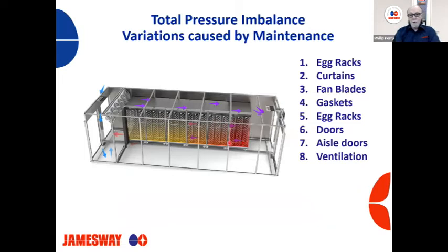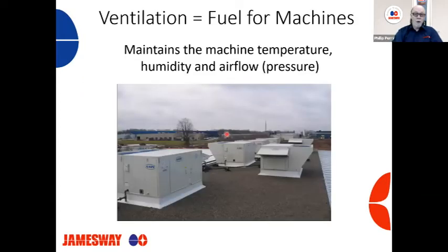Ventilation. I want to take a little bit and talk about the ventilation aspects of the machine, our intake and exhaust. It's very important to the operation of these pressure cabinets that we're running the correct pressure outside the machine. This is where a lot of Band-Aids come in.